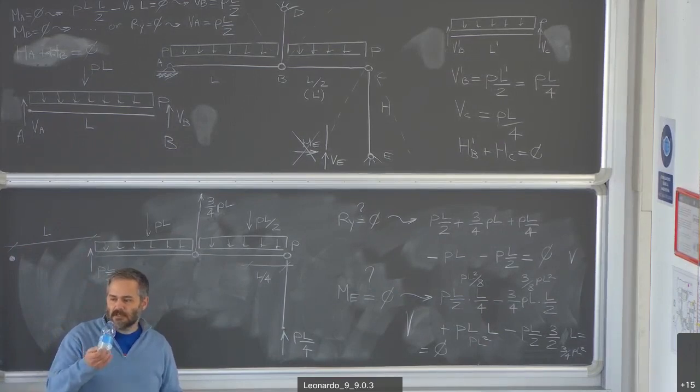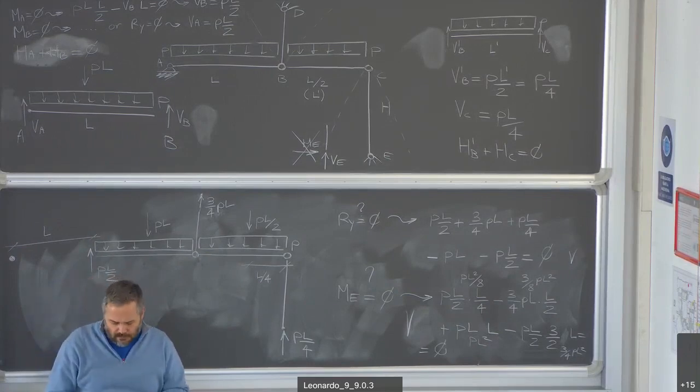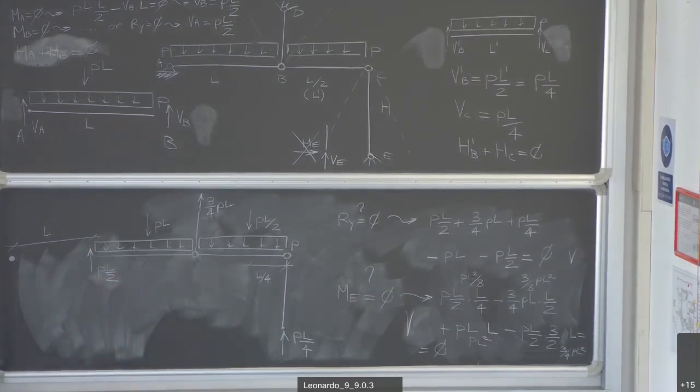I have a general question. Tell me. So, if you're doing the moment equation, you don't take the forces that are on that point. No. Why? Because the moment is always the product between the force and the lever arm. But if the force is applied at the point you use as the reference point for calculating the moment, or when the line of action of the force passes through that point, then its contribution is zero. Okay?